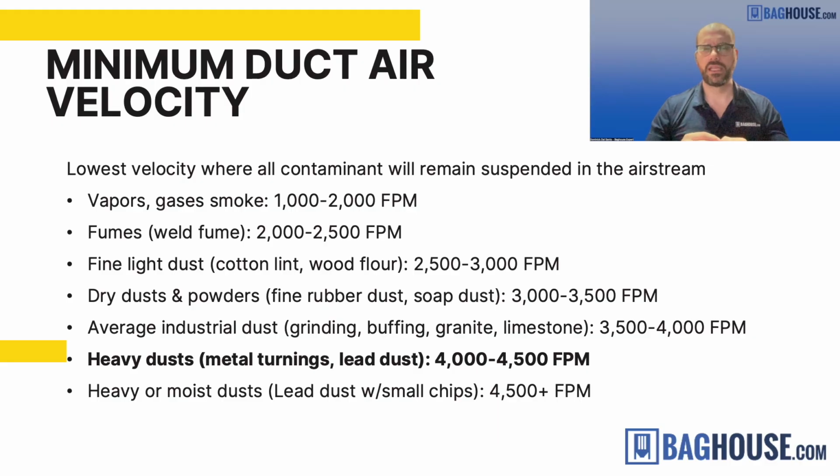For that reason, we usually recommend a conservative approach and to just use a speed of 4,000 to 4,500 feet per minute in all of the dust collection system. If you do that, just about every kind of wood product, chips, strips, fine dust, heavy wet wood, dry, light, fluffy wood, whatever you're sucking up is going to stay suspended in the air, and you won't have dust dropping out, the product building up in your ductwork or on the floors by your pickup. So that's how we take the chart that we saw earlier.